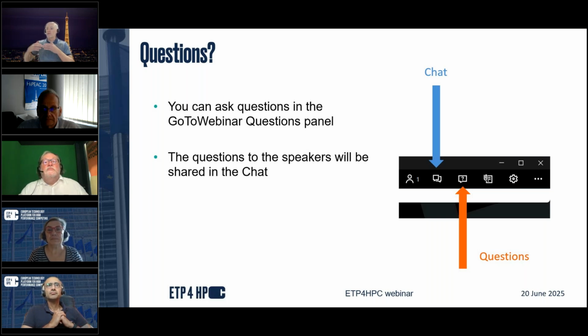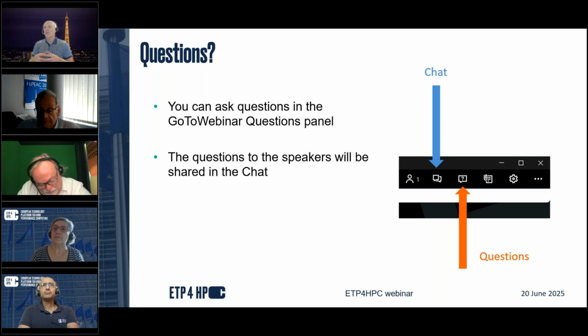Then on top of that, everything from the manufacturing ecosystem has to be in place. What's a known good die? Who's responsible for what? Who's doing the integration in package? How do you do BIST? Who tests the interconnects? What's core zero? There are a number of things that have to be standardized across this SoC before you can do blind builds and have things work together. A lot of them aren't complicated, but they have to be agreed.